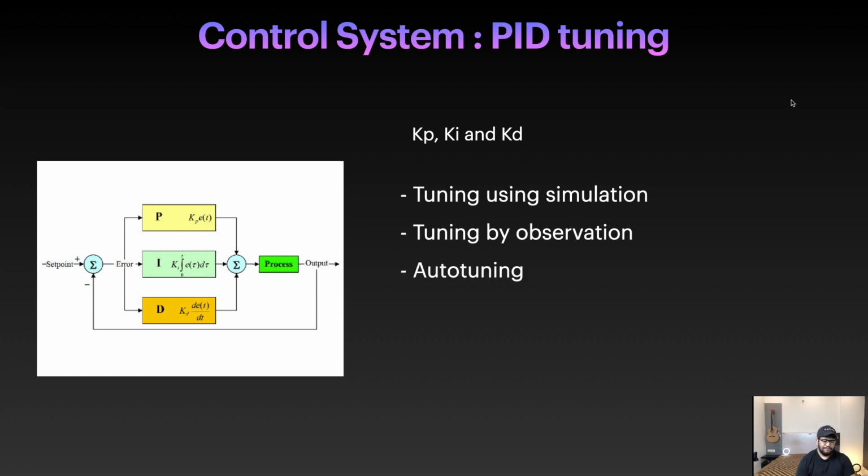One thing that was very common a couple of years back, when new people were coming into this hobby without a technical background, is that they did not understand KP, KI and KD and PID tuning. So some firmware has a feature called auto tuning. You take off your drone, bring it to a certain height, and switch the auto tune on. It will do some motion in all three axes, and based on that motion it will set the values of KP, KI and KD for you. But the disadvantage is that auto tuning is not very accurate. It's a good ballpark number, but not very accurate.